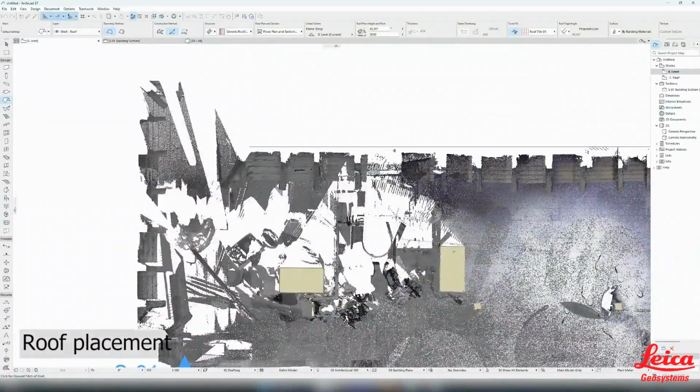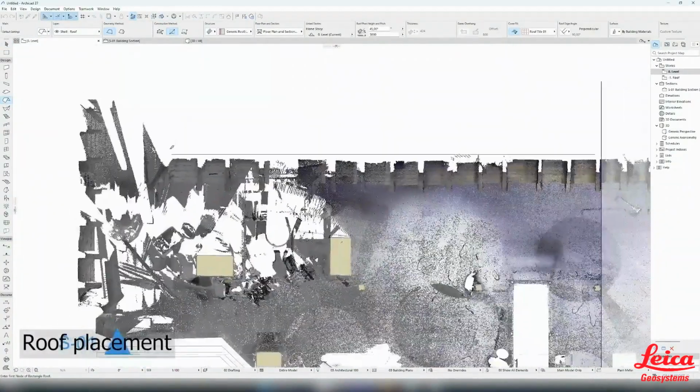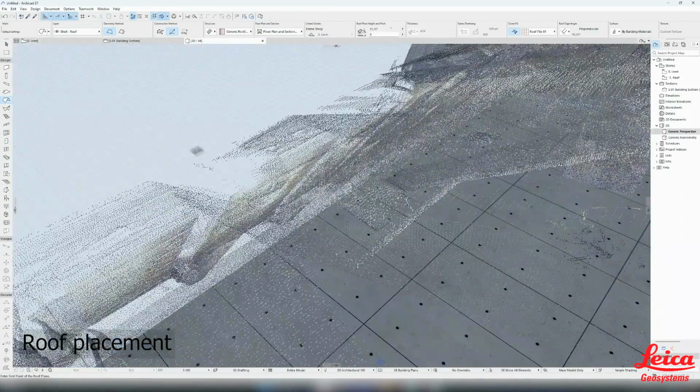First of all, when selecting the Roof tool, we place the axis, which will set the direction for the geometry of our roof. In the settings of the roof itself, you can also change the degree of its slope.